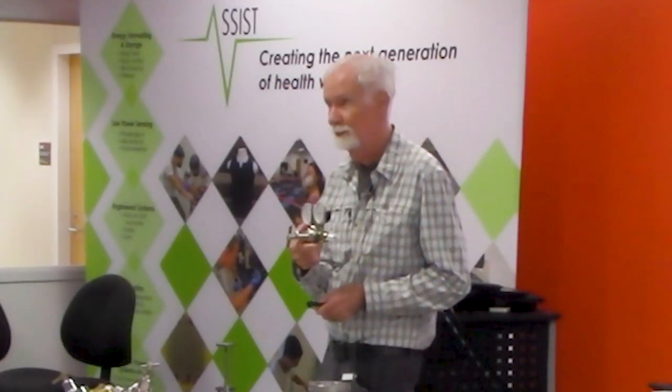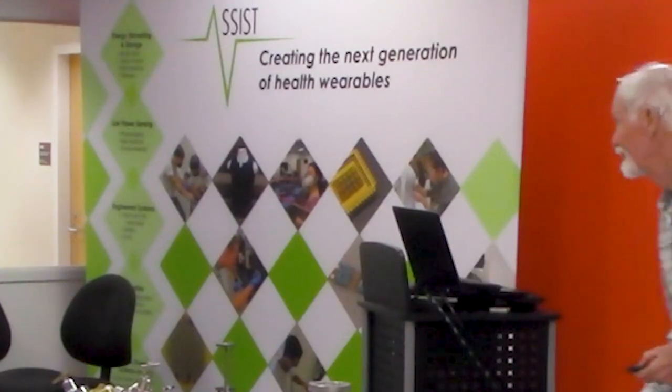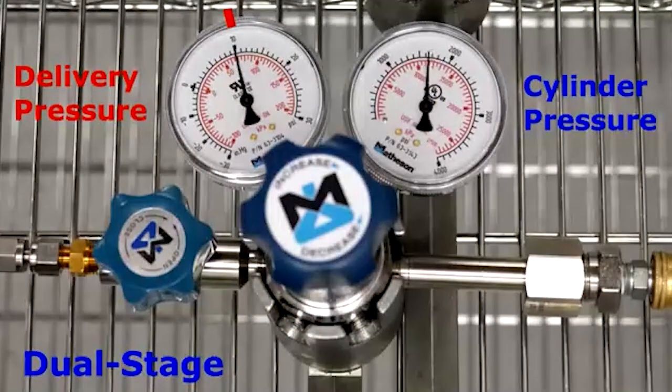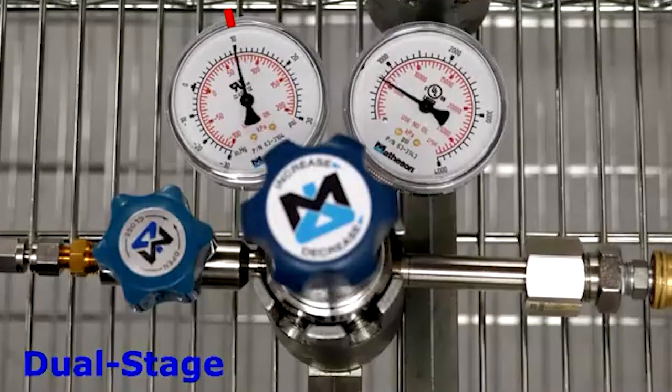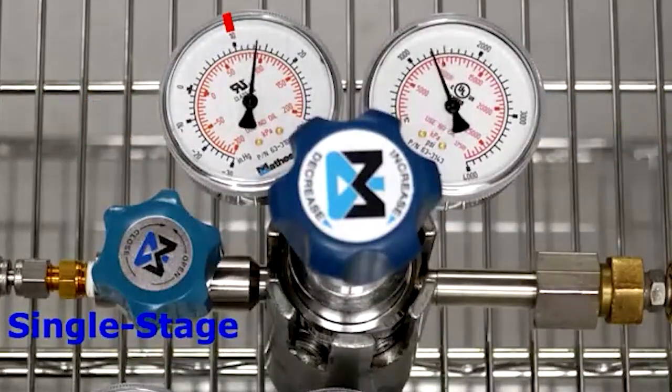Bourdon gauges. Extremely reliable. Anyway, that's what's on all your regulators. There are two types of regulators. I think most of what you'll see are the dual stage. What's the difference? The dual stage, as the gas in the cylinder runs out, keeps the delivery pressure the same.